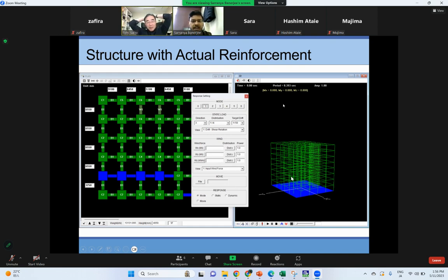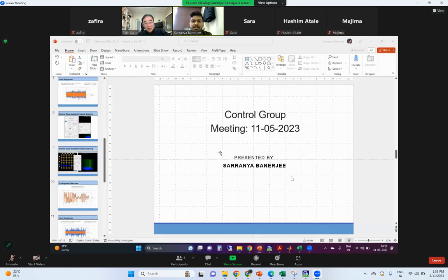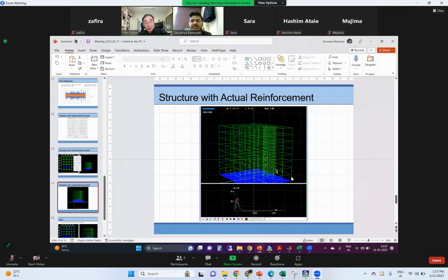That's okay, very solid. Since then I did the nonlinear static analysis, and I am getting this kind of result for 1/50 drift ratio. Which one is the isolation layer? Here, this is uncontrolled, not base isolated. But it looks like yielding happens in the middle of the column. Why such strange yielding? I don't know, I'd like to check.